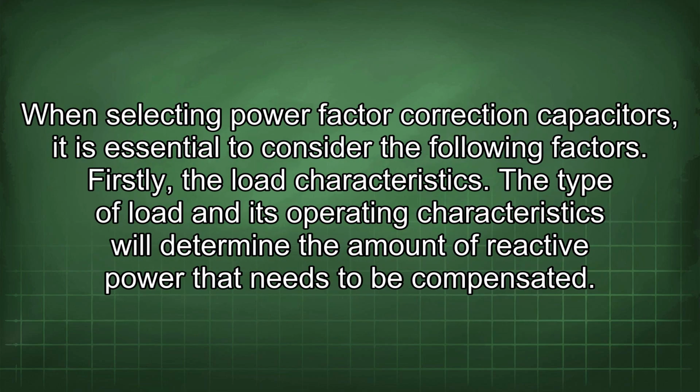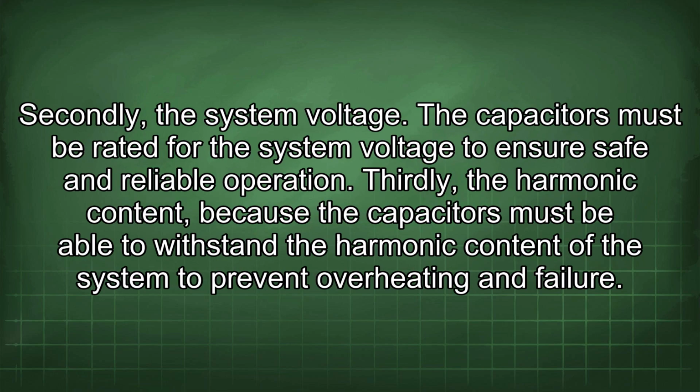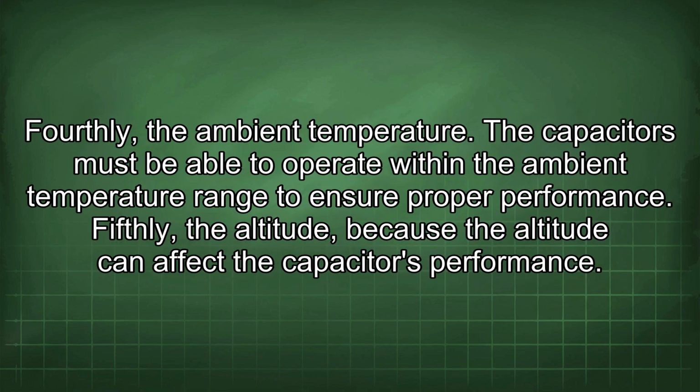When selecting power factor correction capacitors, it is essential to consider the following factors. Firstly, the load characteristics. The type of load and its operating characteristics will determine the amount of reactive power that needs to be compensated. Secondly, the system voltage. The capacitors must be rated for the system voltage to ensure safe and reliable operation. Thirdly, the harmonic content, because the capacitors must be able to withstand the harmonic content of the system to prevent overheating and failure. Fourthly, the ambient temperature.